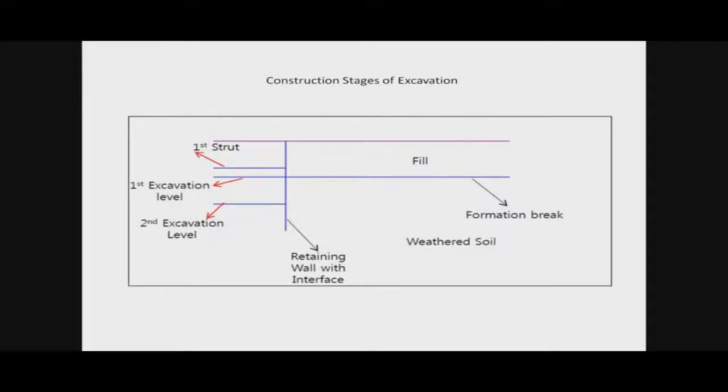So this is the model that I'm going to construct in front of you today. This is a 2D model predominantly, and we are going to perform the excavation in two stages. As you can see here, this is the first level of excavation and this is the second level of excavation. We are going to model a retaining wall, and we will model the fill and the weathered rock, and we will also apply a pressure load on the top of fill, and then we will check whether the displacements and the stresses developed in the wall are in range or not. So let's start the modeling of this type of 2D structure in MIDAS GTS.